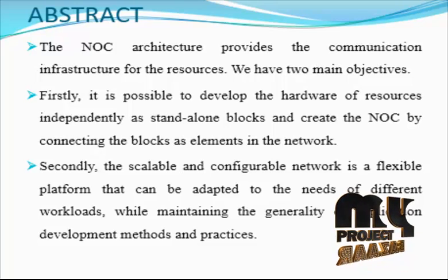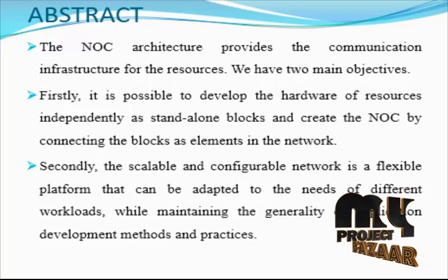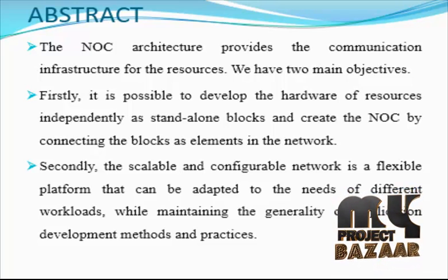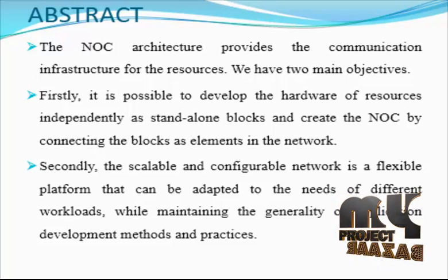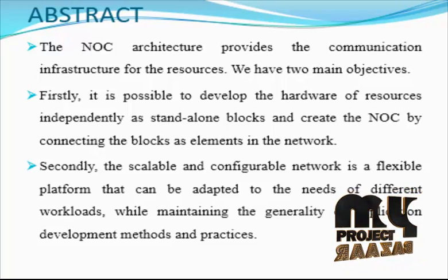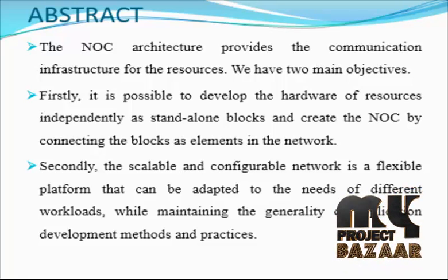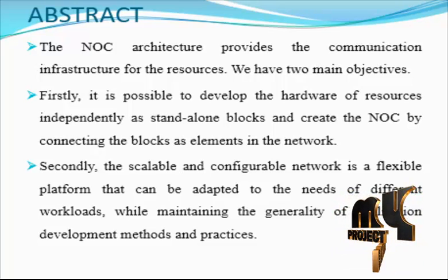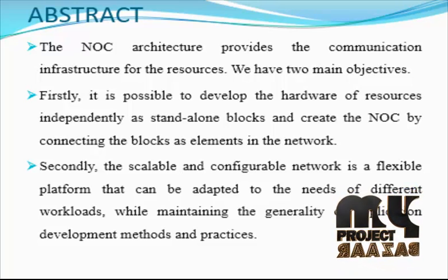In this paper, we present MACS, a highly parametric NOC switch architecture that provides reduced data transfer delay and latency, and increased design flexibility and scalability as compared to previous architectures by combining and enhancing several NOC design strategies. MACS enhances inter-processing element communication using a circuit switching technique with minimal adaptive routing and a simple and fair resolution algorithm to maximize the bandwidth